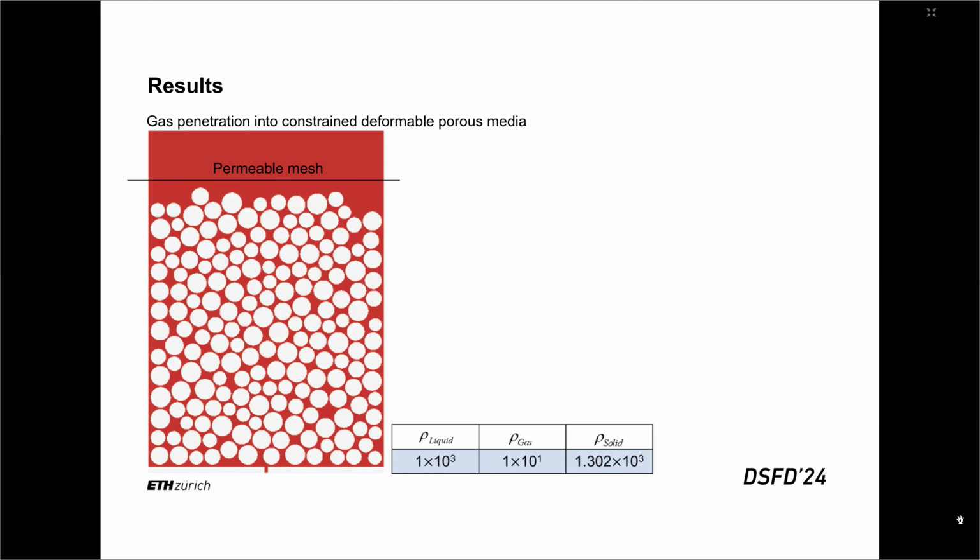We can get the average density through the fluid nearby, and the velocity can be calculated from the particle's velocity, and we can get the equilibrium particle distribution function. Then we average the neighbors' non-equilibrium part and add it on to this equilibrium particle distribution function. Am I clear? Okay, thank you.